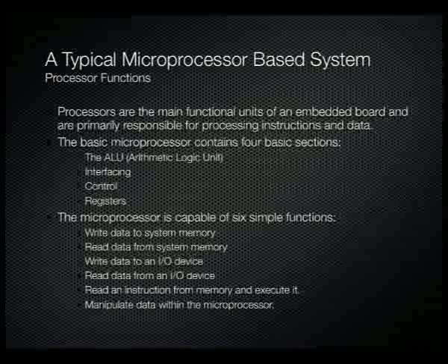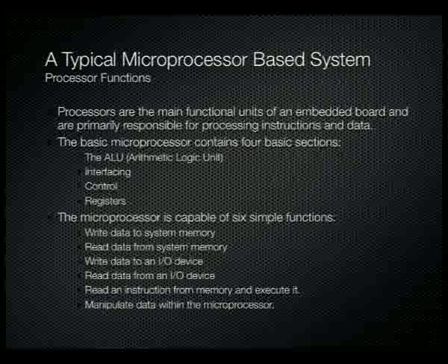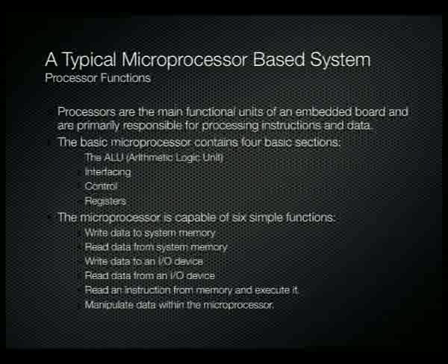We then have an interface section as well. The sole purpose of the interface section is ensuring that the processing core is communicating properly with the I/O devices as well as our memory devices, to ensure that data is transmitted at appropriate times, that we don't have data corruption, and that things are received correctly. So we have a whole section defined purely for ensuring that the processing core is communicating properly with the other components inside the chip.